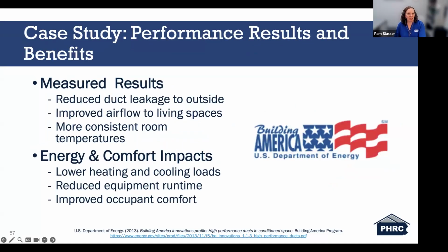When those strategies are applied properly, we start to see measurable improvements in system performance. The results from this study clearly show the benefits of bringing ducts inside the envelope. Duct leakage to the exterior is significantly reduced, meaning more of the conditioned air actually reaches those living spaces. Airflow delivery improves, and the temperatures throughout the home become more consistent, which directly impacts occupant comfort as well.